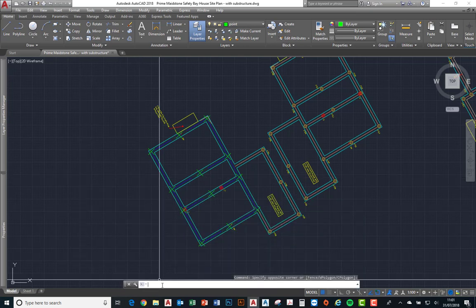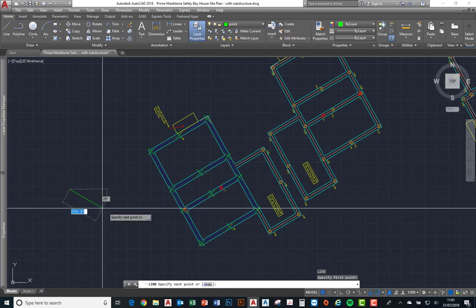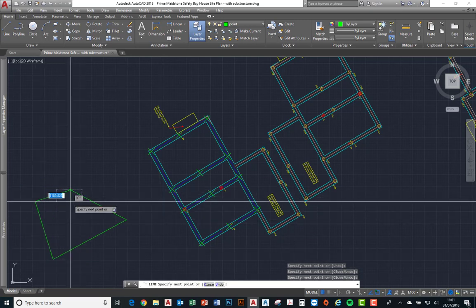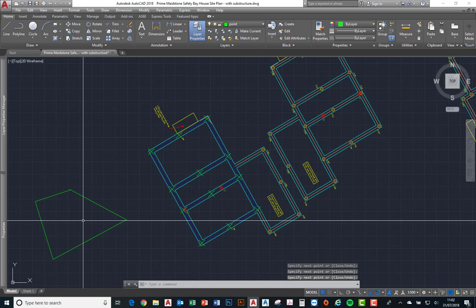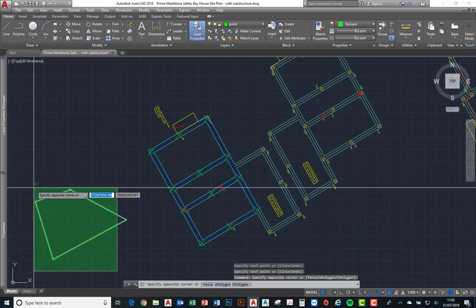If I create a line and then hit F2 again, you'll see that I've only got a few of those IDs left that I've interrogated, and then it goes on to line and other information. So definitely when you've interrogated your points using multiple ID, go straight into F2 and photo them or output them to Word, otherwise you'll lose that information because it's not actually held anywhere. It's just showing you your last commands.